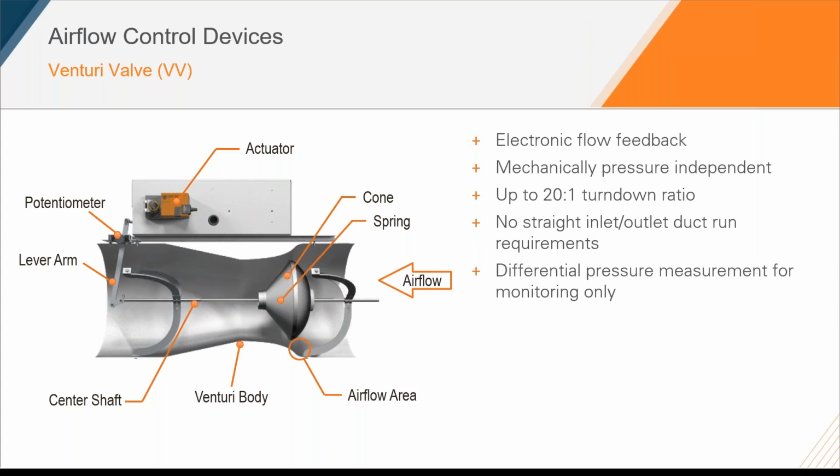And then lastly, with these valve technologies, the biggest thing to know, to ensure we can maintain that mechanical pressure independent nature, is that we have to ensure that we have at least the proper amount of pressure through the valve to get us that compression through that spring. So with these valve technologies, the monitoring you're going to get is the pressure measurement, the pressure monitoring through a high and low pressure port. I'll talk about that later in this presentation.